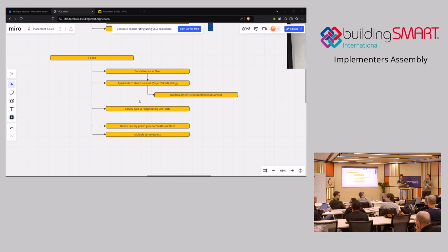Would you, if there was a disagreement, so like for the alignments, right? The primary was the relative placement, and then the linear was sort of a secondary one. Here you'd have the CRS, and you'd potentially also have a placement tree. Would you just forbid that? If there's two buildings with two CRSs, there can't be any transforms in the parents? Or would you say that basically, if you hit a CRS, you reset the transform?